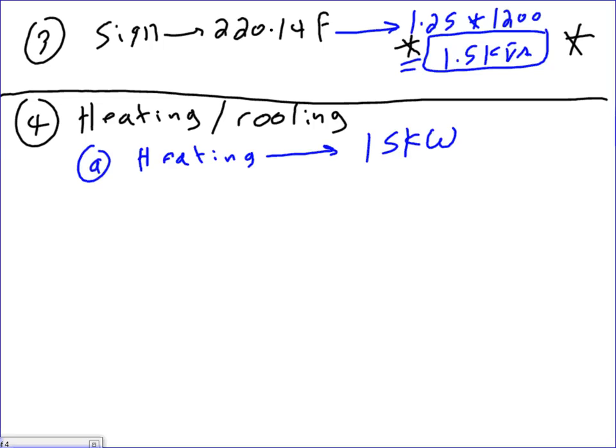And since it's heat, guys, you can easily put 15 kVA and highlight this. 15 kW and 15 kVA, since it's resistive heat, the power factor is 1. The kVA and kW are the same. Had it not been like this, you can't make the W equal volt-amps. But it's heat.